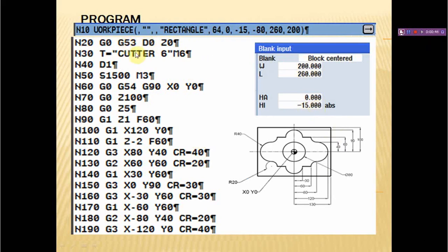And then move the cutter to a reference point, selecting the cutter, end mill cutter of size 6 mm with the offset number, giving some speed to the spindle with the clockwise direction, bring back the cutter to X0, Y0. G90 is absolute command. So if you write G90 from this reference point, we need to set all the parameters. G54 is work coordinate system.